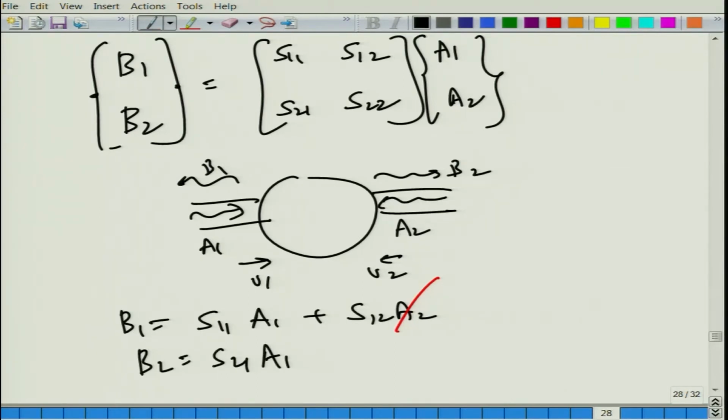What it means is that we are exciting the system, let us say this muffler proper, this is the inlet port, this is the outlet port. We are connecting the inlet to the engine exhaust, and this is the tailpipe. So, there are no reflections.